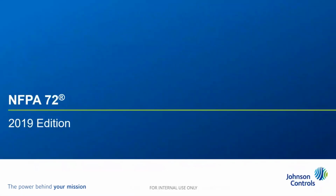So now we jump over into NFPA 72, the 2019 edition. A lot of what you're going to see here is pulled directly from NFPA 720. When we worked on this, I say we, I was very involved with 72's 2019 edition and pulling this in. There were several task groups that were developed, and everything that was in 720 had to be pulled into 72, which meant let's put it into the fundamentals. How should we supervise this? How should we battery back it up? Chapter 17 for initiating devices, Chapter 14 for how do we test it, Chapter 18 for how do the notification appliances work, and just on and on and on. So it really was a huge change to add all of this into 72.